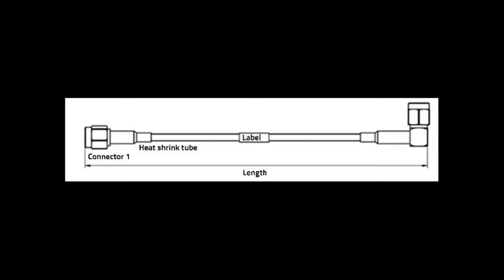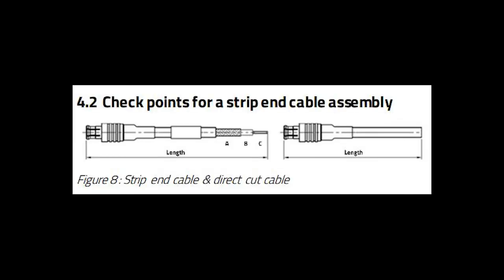The strip end could make assembly easier for the user according to these types of strip. First is the stripping dimension, and here usually the tolerance is specified. In the direct cut, the user strips or performs assembly using another method. The tinned braid or the pigtail strip assembly allows users to quickly make the cable perform without a connector or even proper shielding.